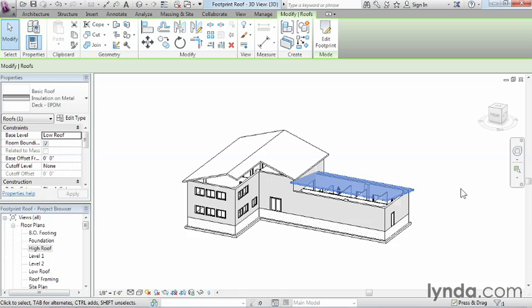The footprint roof is very similar to a floor slab, except that typically you're going to apply slope to it. You use the Define Slope checkbox to make any one of the edges a sloping edge, and that edge basically is treated like a piano hinge. When you click Finish, Revit will figure out the 3D geometry from your various sloping and non-sloping edges.